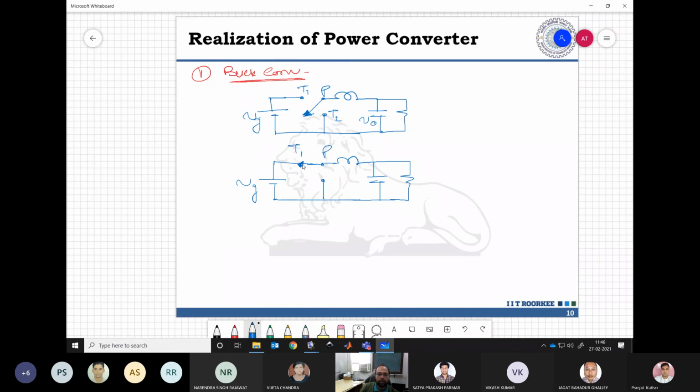This is where P is connected to T1. Now we see what the voltage and current polarities are in this situation. So we have current flowing in this direction and we have the blocking in this direction for PT2. So P is at the VG terminal whereas T2 is at ground. So the polarity of voltage which is getting blocked through PT2 is like this.